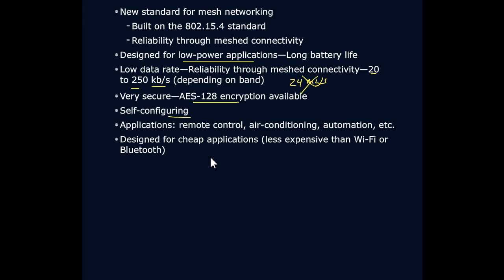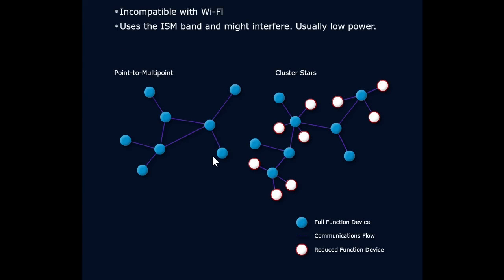Again, low power, simple installation, literally designed to allow for throwaway kinds of devices. When we work with a ZigBee network, it is in North America using the 2.4 gigahertz range, so it does have the chance to interoperate in an incompatible way with Wi-Fi. In other words, it can introduce interference in your Wi-Fi network, hurt it, not help it, just like a Bluetooth network can do, and certainly something to consider.